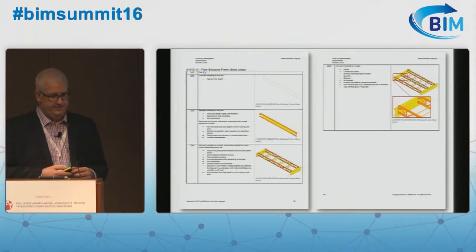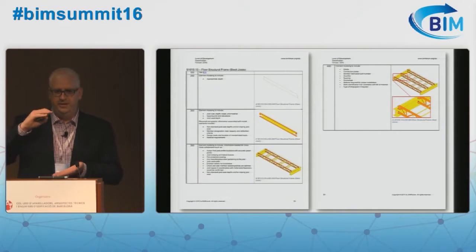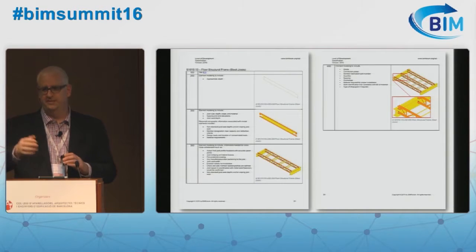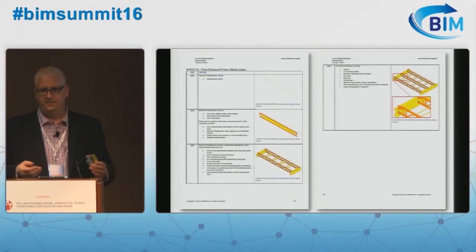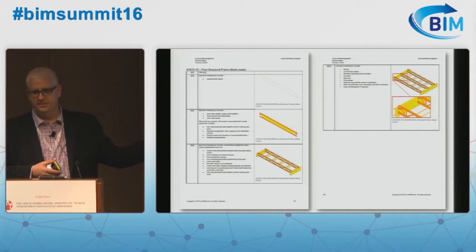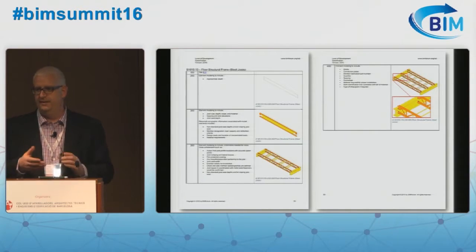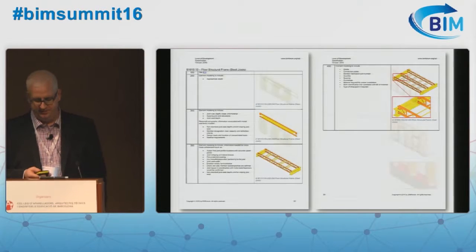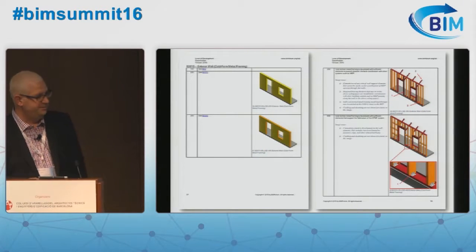As we go through an example with a floor, we may know that at 100 we just have a generic space that's calling out a floor slab. As we move along, that structure starts to define itself as a joist that's running in a certain direction. At LOD 300, we identified it as a steel joist. We know that different joist manufacturers have different webbing configurations, so we can't rely upon that information at 300. So we see that information start to come in at 350 because now it's specific about the assembly that's going in. And then 400 starts to identify all the additional components that are there. And these methodologies start to be very continuous.